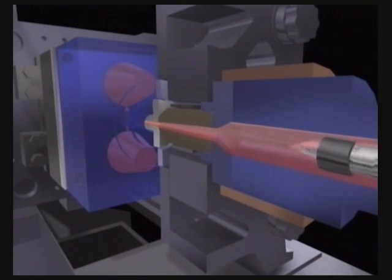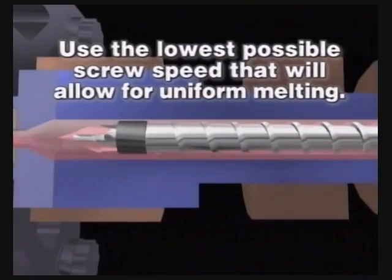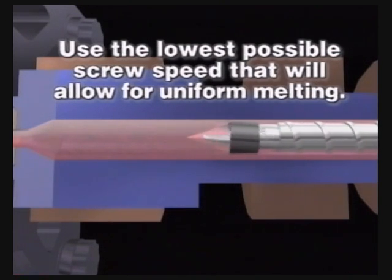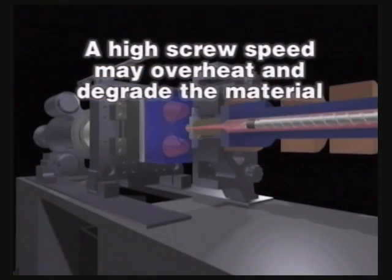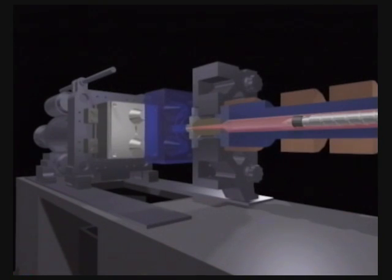To determine the correct screw speed, refer to the processing information supplied by the material manufacturer. It is important to use the lowest possible setting that will allow for uniform melting. A high screw speed may overheat and degrade the plastic material. This will cause dimensional problems as well as a reduction in the physical properties of the material.